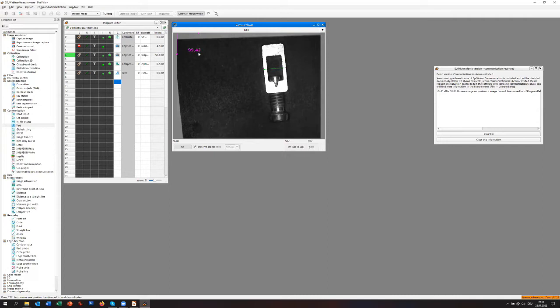Depending on the pixel size, we can calculate this later. We know now this is hundredths of a millimeter, I would assume. That means if you use this value, you say 99.4 plus minus 0.1, then you have this hundredths of millimeter accuracy. You don't see the millimeters, you see only the pixels. The next step will be we calibrate it in millimeters and then you see the millimeters.